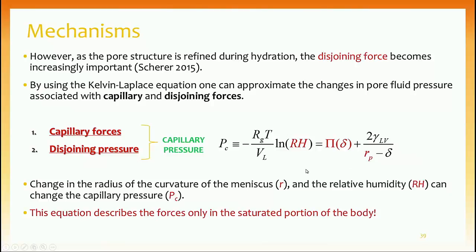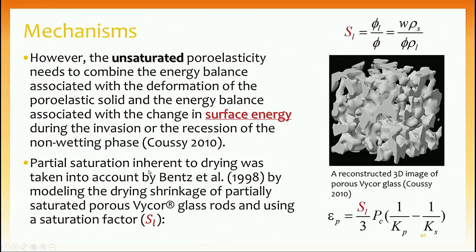So these two forces are basically describing the forces only in the saturated portion of the body. But in reality, we have a partially saturated system. And there is another mechanism that can play a role, and that's called the surface energy of the system. The degree of saturation, which is basically the ratio of the water filled pores to the total porosity, is shown here. And it was taken into account the very first time by Dale Bentz's team in 1998.